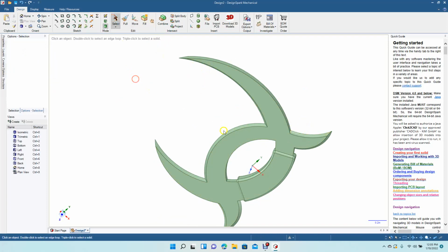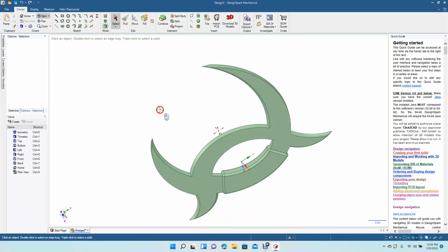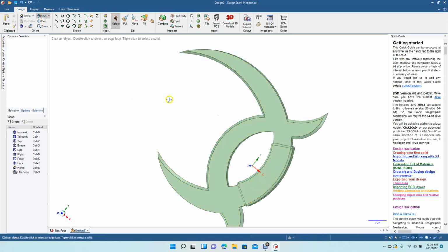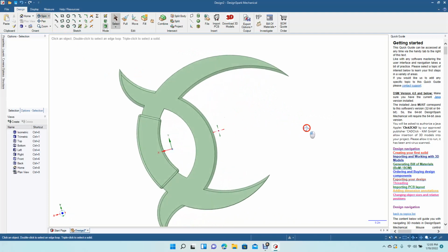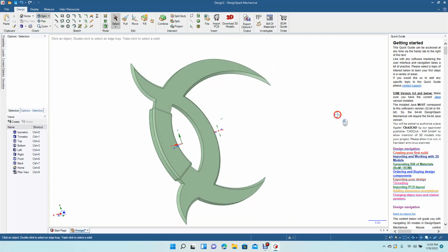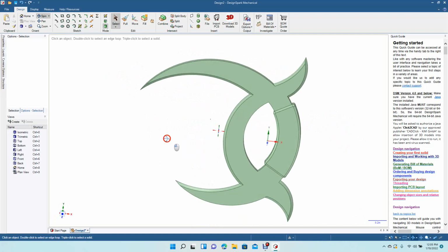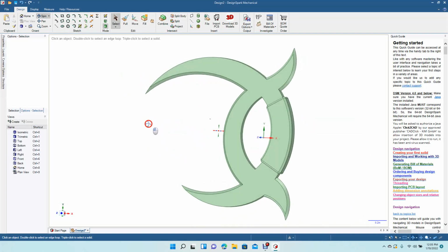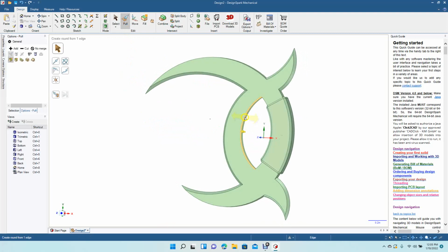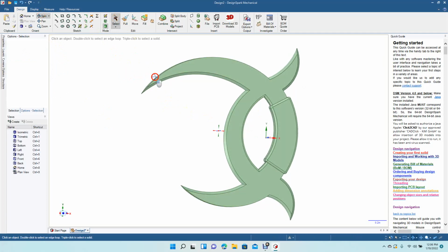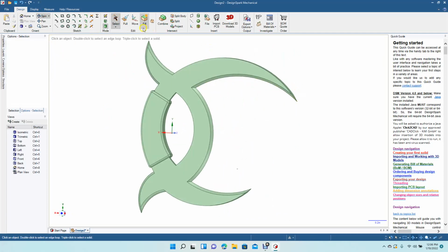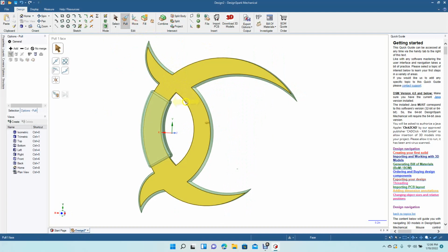Okay, this don't look too bad. Go ahead and spin. So I'm going to keep the middle part. Doesn't need to be chamfered. Okay, that looks pretty good. I think I will put a fillet in here though. Hold down the control key. 0.02 fillet. Spin that around, do the one on the back side, and then we'll be done.